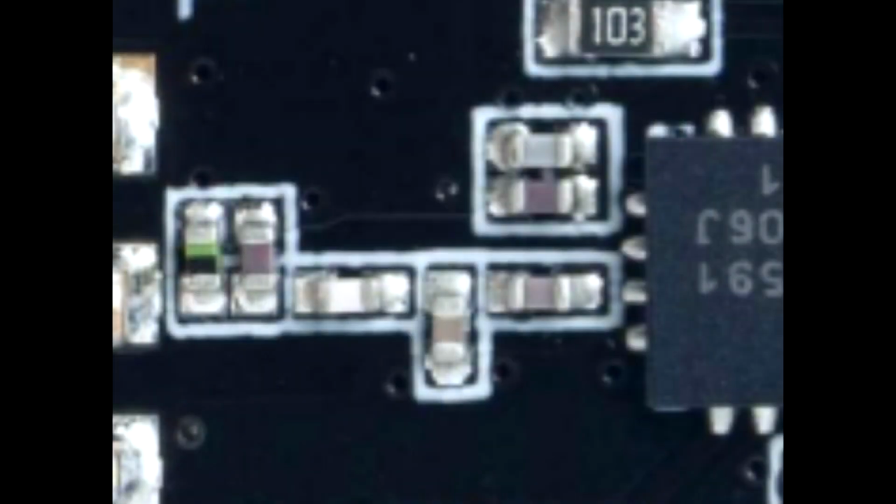And then over here, this is the edge, this is the SMA connector, or actually it's an RP SMA because it's 2.4 gigahertz. Between there and the CC2591, there are inductors and capacitors. And how do I know how to build that network of inductors and capacitors?